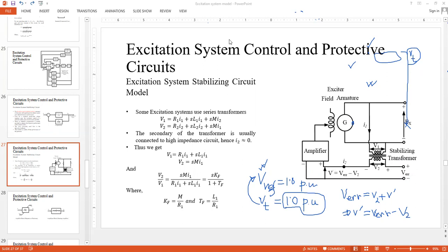Now, in general, there are several types of amplifier, as we know: voltage amplifier, power amplifier, current amplifier. In this case, we are actually amplifying the input voltage error, so this is nothing but a voltage amplifier. And from the basics of the voltage amplifier, we all know that the input impedance to the voltage amplifier is kept to a very high value.